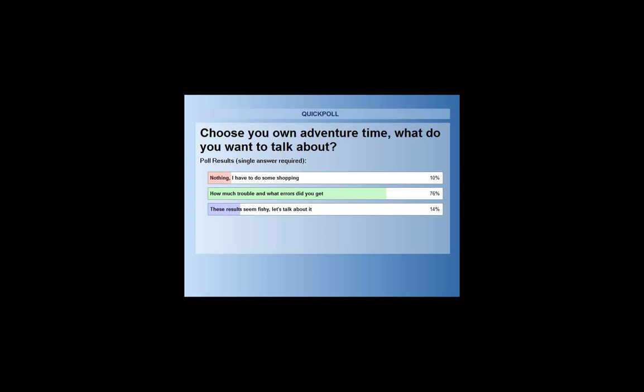Okay, so we're talking about troubleshooting. Yes. So let's go and start with the geometry. The first error that I hit was a meshing error. And that was coming from this geometry, because while I'm getting going, I just need to see what the analysis is going to do. Am I going to fail based on this simpler geometry? I'm probably going to have issues when I make it more complex. So I just tried to mesh it, and sure enough, it failed. It failed on surface meshing.